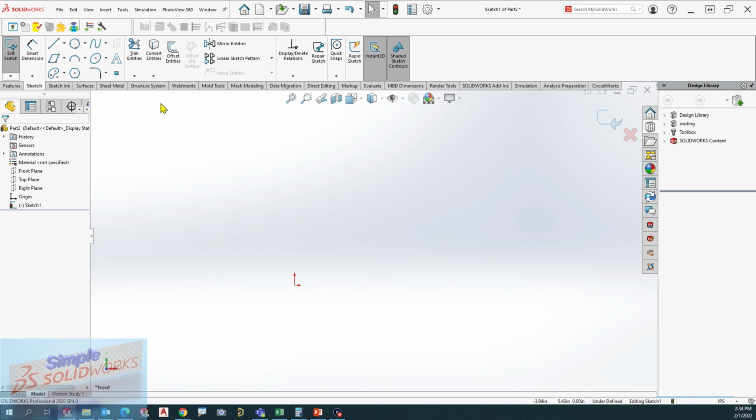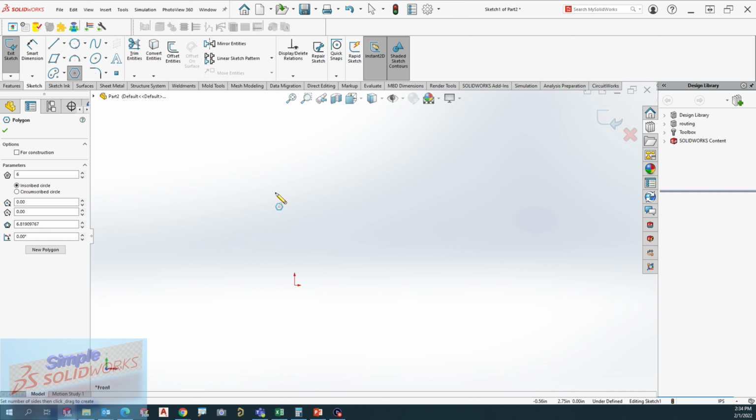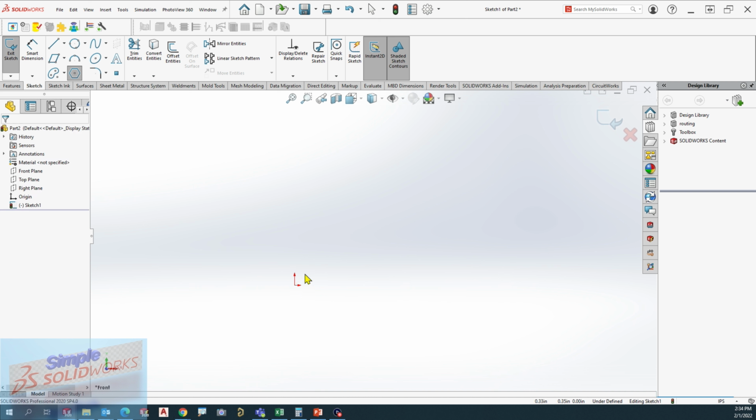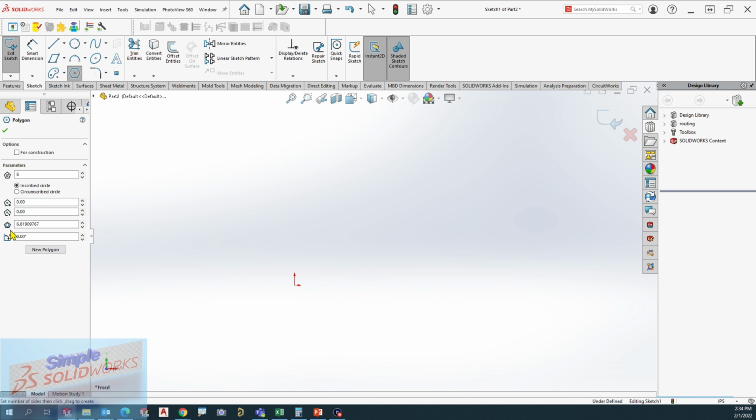It's a very basic polygon that you can get out of with SolidWorks. If you notice here, also in this command, you got these options here. If you pick on this circle here, look at how it changed the circle symbol here, right? Because I put circumscribe, it puts it inside of the circle. Therefore, the symbol change tells you what it's got to do.